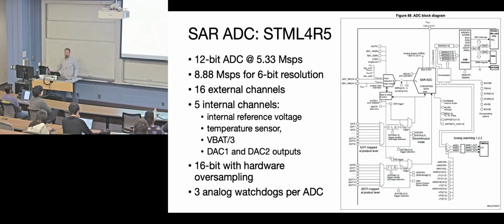Are the DACs in the chip different than the ones that the ADC uses? Yes, they are. It's much easier from a design point of view just to take a DAC and make it specifically for an ADC rather than trying to time multiplex the usage when you're trying to access it and send out analog values and then have it choose something internally. So, that's a good question. It's all just wrapped in that SAR ADC box.